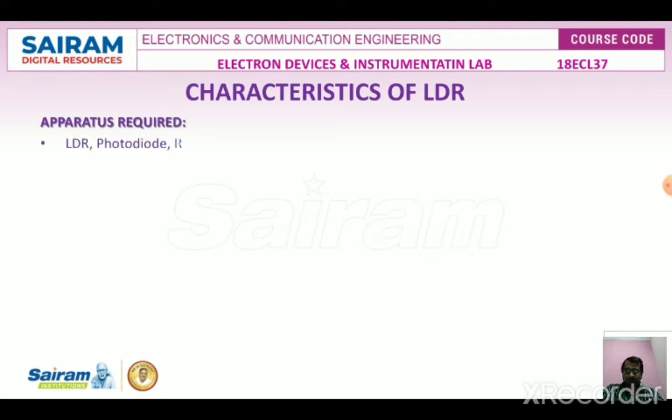The aim of the experiment is to design and test the positive and negative clamping circuit for the given reference voltage.